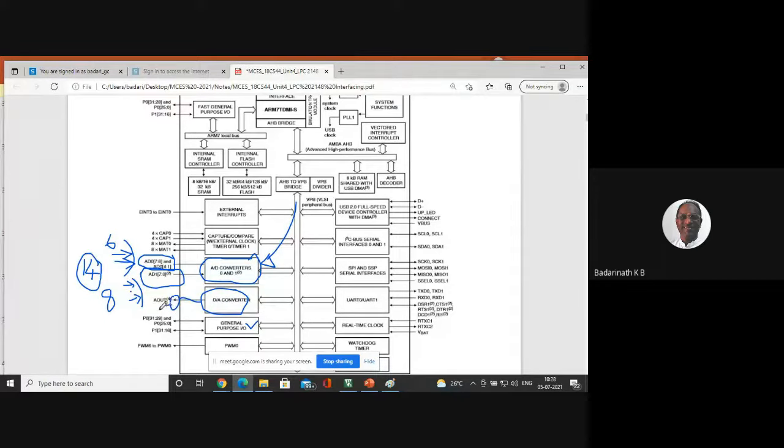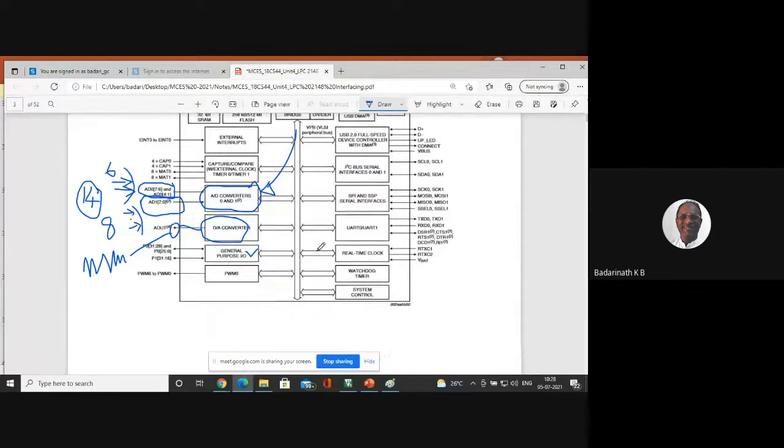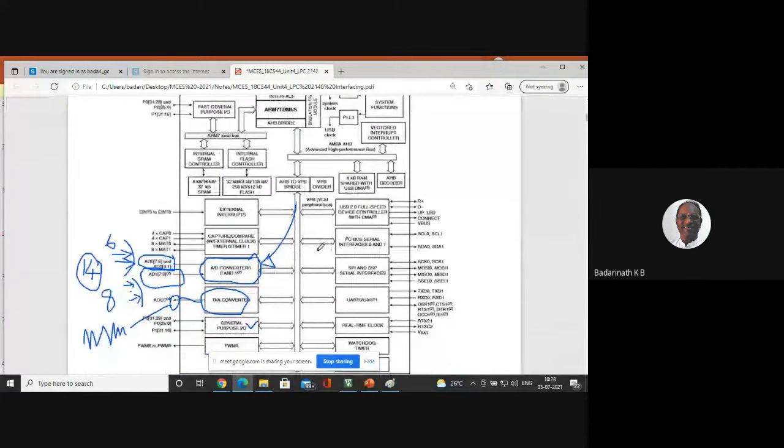If you check this pin on the oscilloscope, you can get different waveforms and pulses. If you look at the complete 64 pins of the LPC2148, no pin is available which can generate analog data except the single pin called AOUT. So if you want to produce any external-world analog signal, such as voice, or something that can control a motor, anything analog in nature which changes with time, there is only one pin available among the 64 pins, that is the analog output pin.